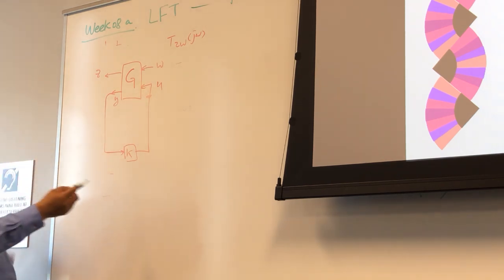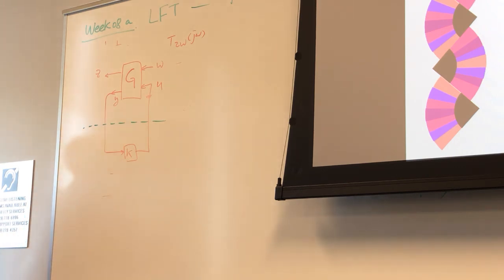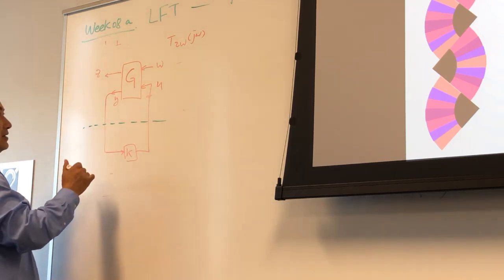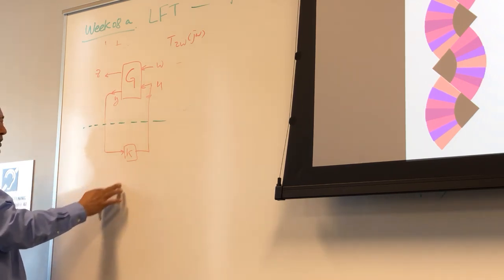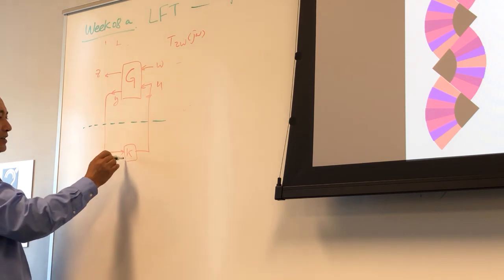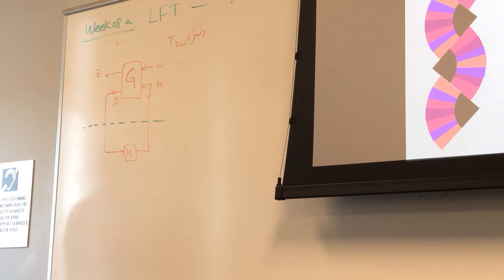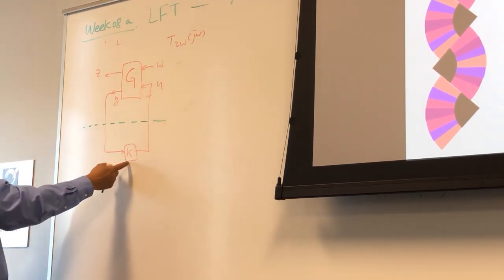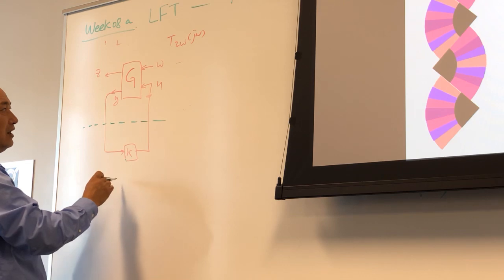So I pull out the K. Then I can discuss my stability. According to the small gain theorem, I know whether the K is considered as a robust stabilizing controller, making the overall system stable. Given K, I can check that. Okay, it's easy.